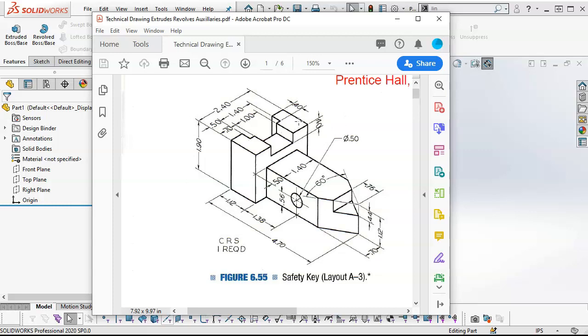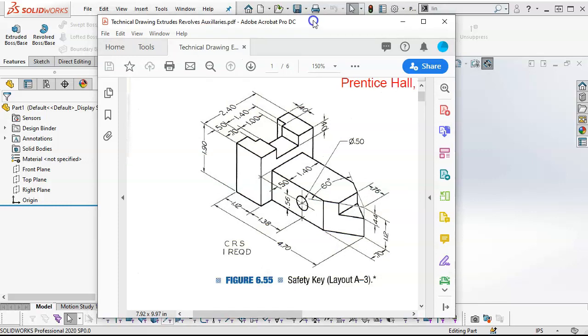And the figure we can break into a couple of major components, and traditionally that's the way I would start. I see kind of the rectangle. If I note that this is the top plane, then over here would be the right plane, and the front plane would be somewhere. And because we have symmetry, really I want the front plane to go right through the middle of the part. Anytime I can utilize that symmetry, that's going to be helpful for us. So I'm going to fly this out of the way,